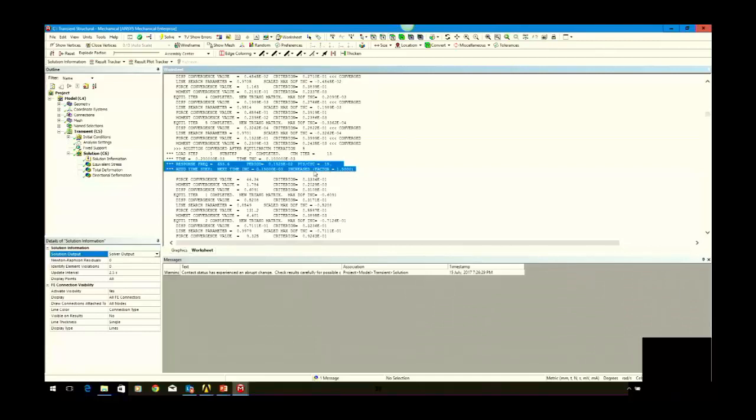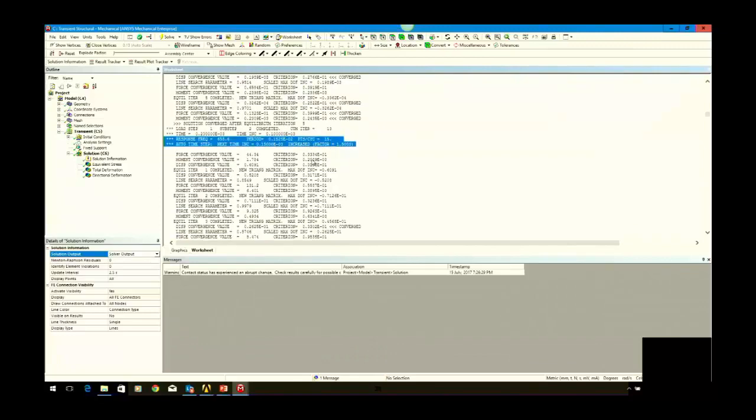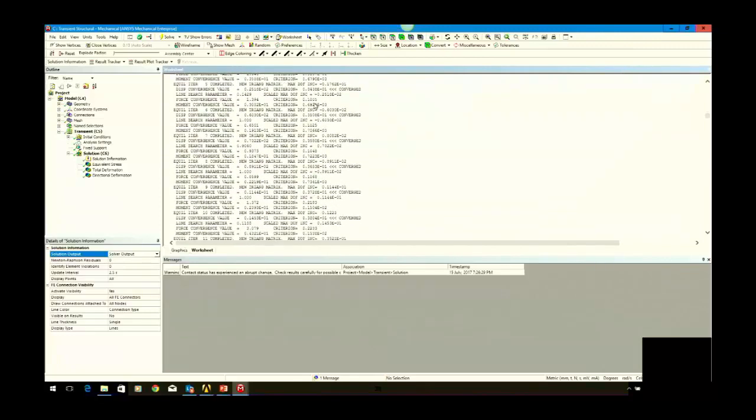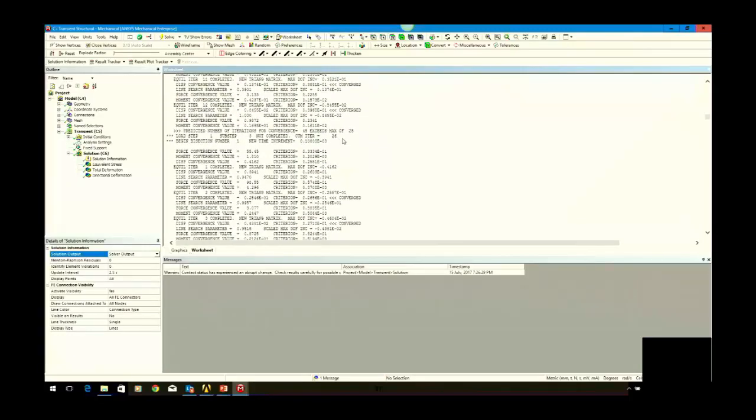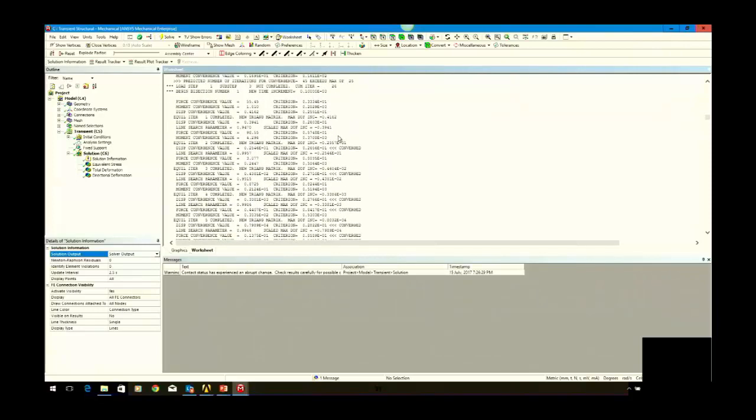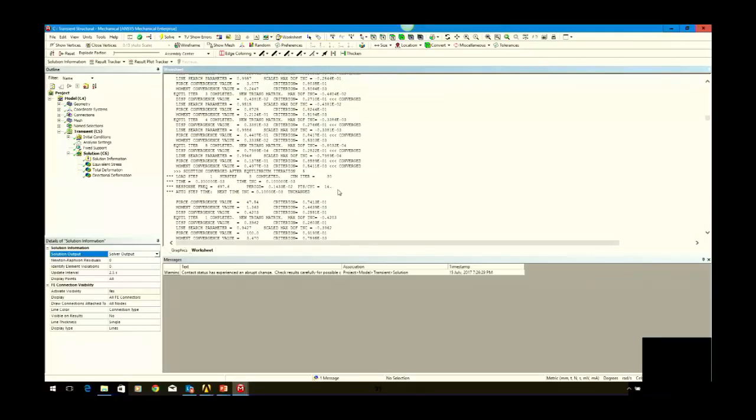The solver normally likes to have at least 20 points, but sometimes it will adjust the time step anyway. Here it's got 14 points per cycle. Normally the recommendation is to have at least 20. The solver, I think, only requires around 10, and only when it gets below that will it adjust the time step, if you've given it the ability to do that.